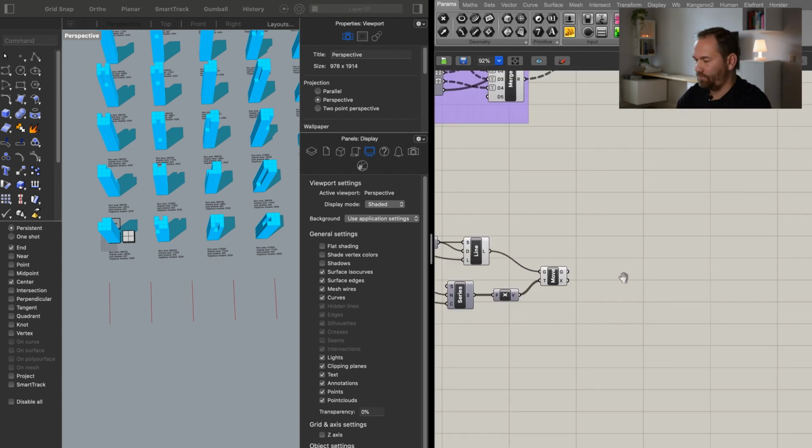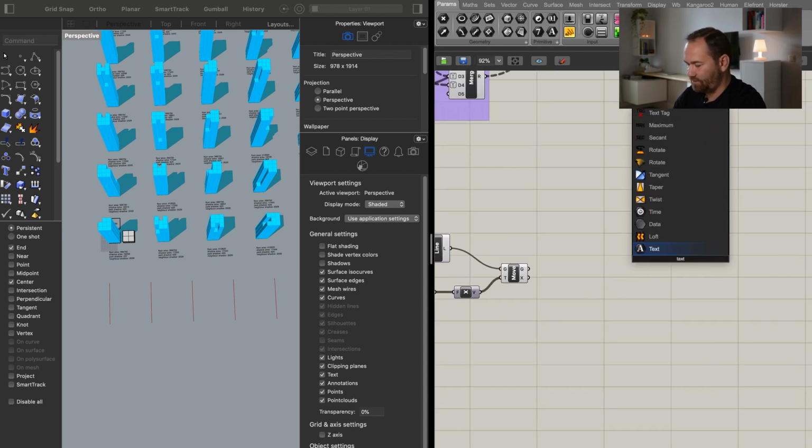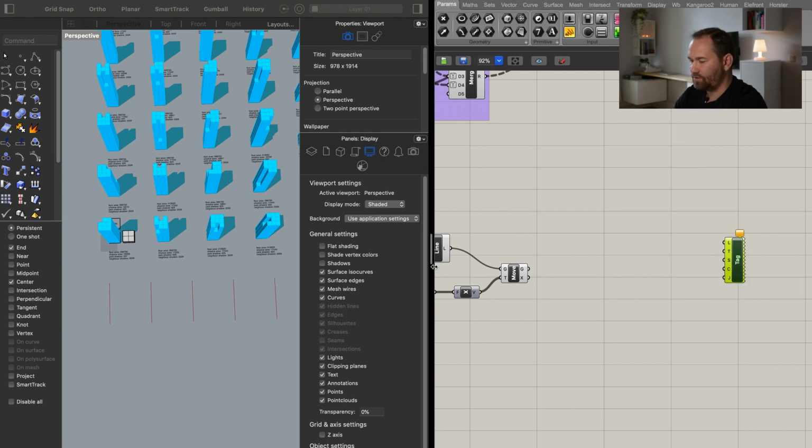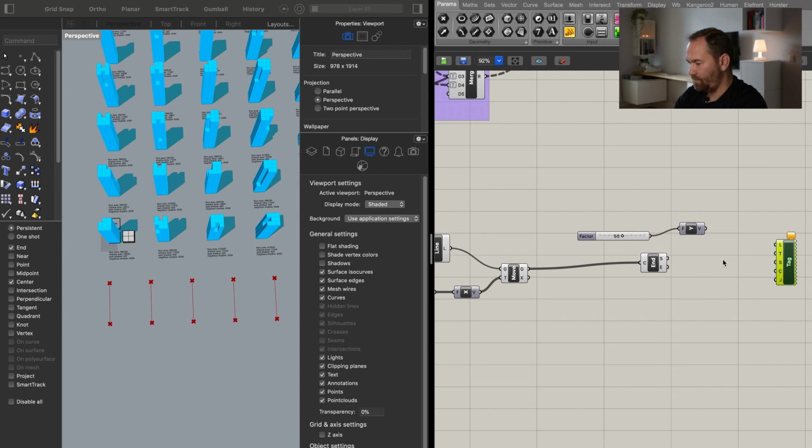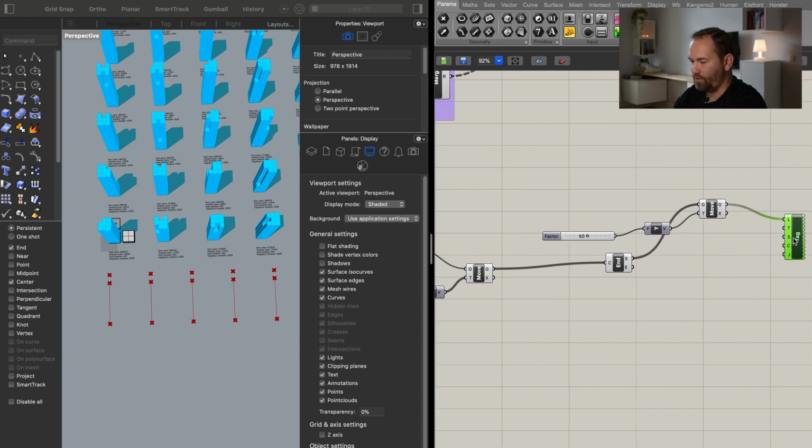Next, let's label the lines. For that purpose, we're going to take a text tag, 3D text. The location, let's label them slightly up from their starting point. So first let's find the endpoints of these lines. Here they are. And slightly up from the starting point would mean that we want to move along the y direction with maybe 50 units. Move this point, the starting point, and that's the location for our text.